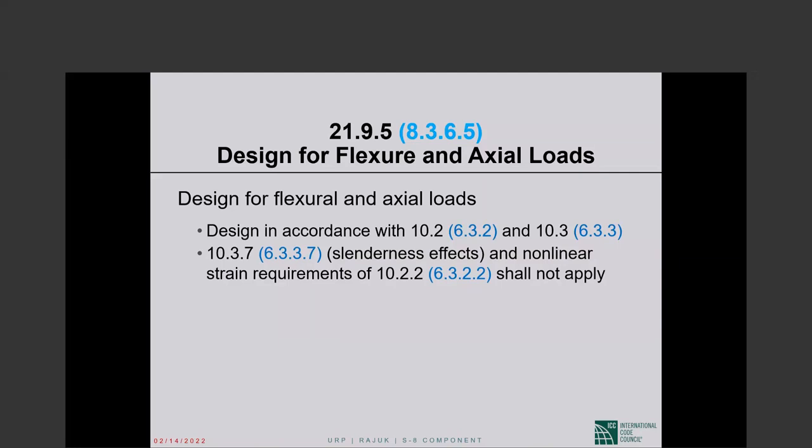The web carries shear for us, and in shear design we actually neglect the flanges. That same shear wall somehow is supposed not to do anything for us when it comes to flexion and axial load. This design procedure was a throwback to the days when shear walls used to be infill frames.